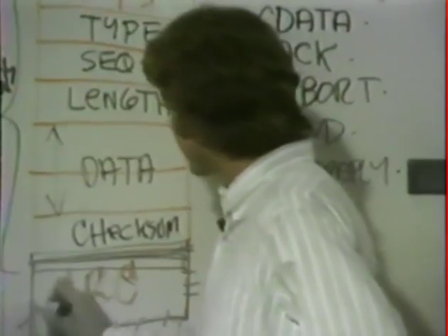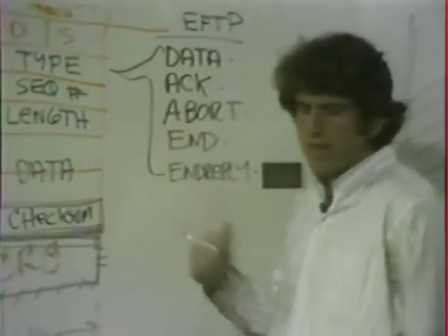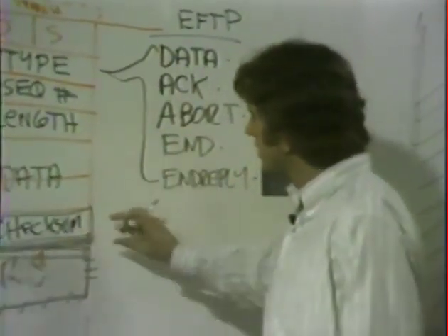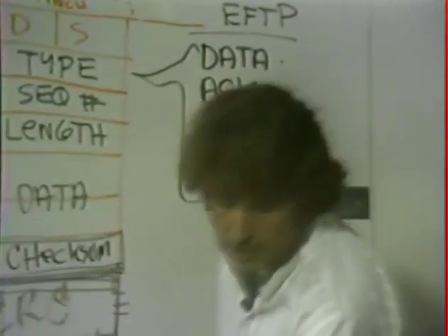And then finally we have a checksum. You'll note that this checksum is not the CRC that I mentioned earlier, which exists only in hardware. This is a software checksum computed in software by the originating station and then checked by the receiving station to be sure that the data in this packet has been received correctly.